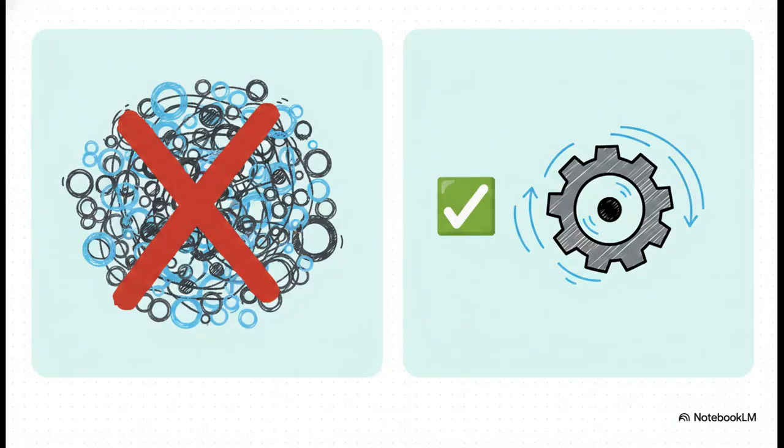Okay, quick pro tip here from the manufacturing experts. Stay away from concentricity if you can. It is incredibly difficult to machine and a massive headache for the metrology guys to inspect simply because it requires deriving theoretical median points. Look, in almost all cases, you can achieve the exact same functional requirements by just using true position or runout, completely avoiding all those unnecessary manufacturing costs.